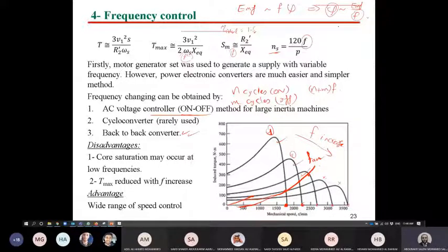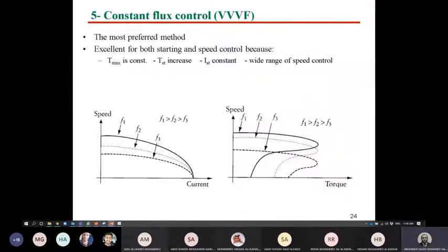If the machine reaches field weakening, the machine will be overspeed, and this may damage the bearing of the machine. However, field weakening is already a control or a mode of operation needed in some applications in industry. Okay, but you have to consider the design of your machine. If you are going to make field weakening for any machine, you have to consider this in the bearing of the machine.